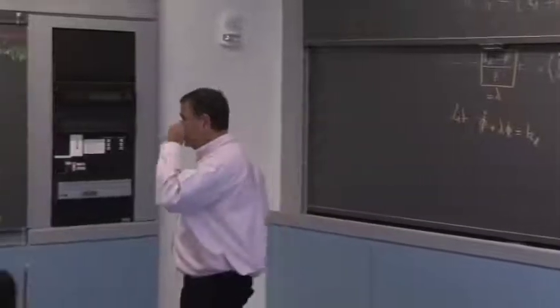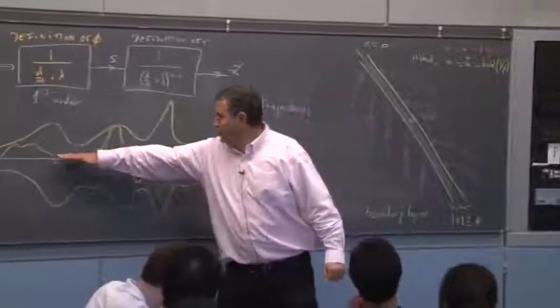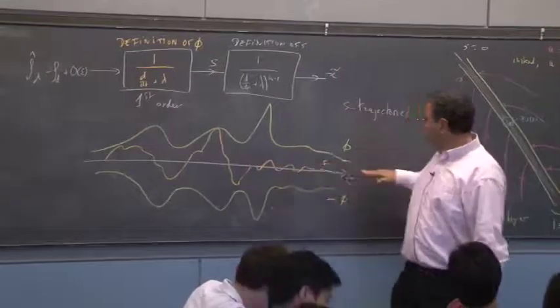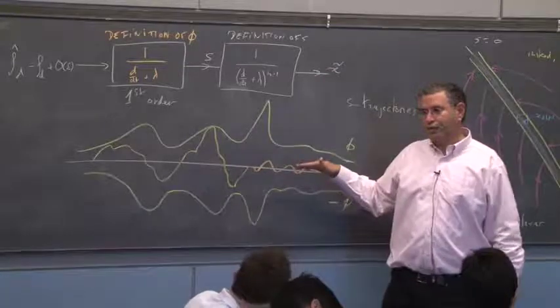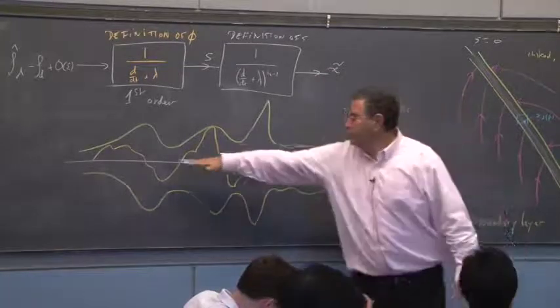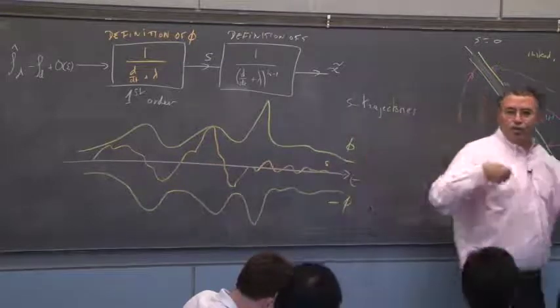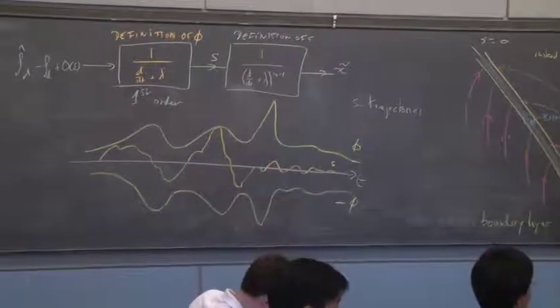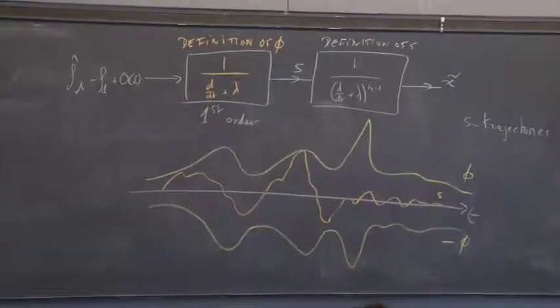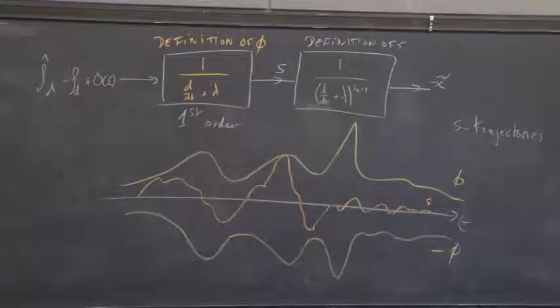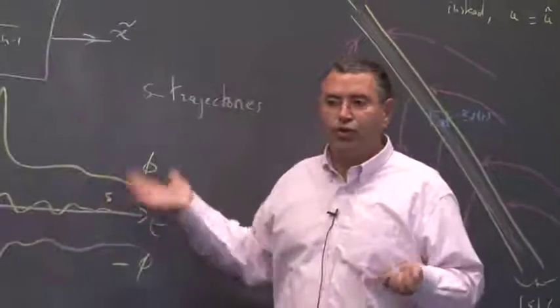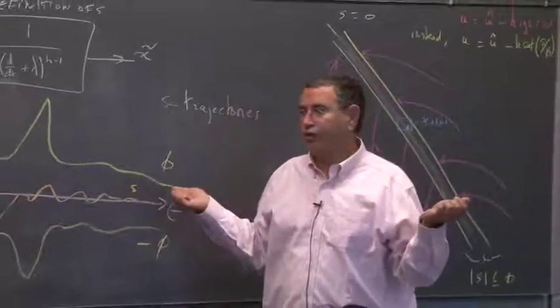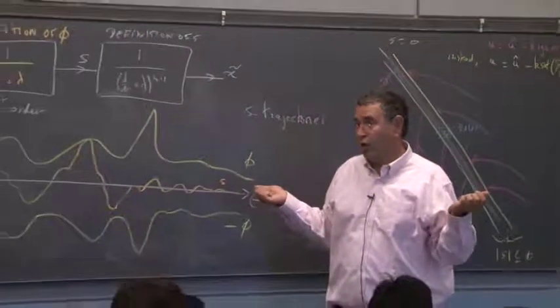First of all, suppose the orange curve is basically along the x-axis in this plot because phi is so much bigger than S, okay? Basically, you don't see the orange curve, right? It means that your assumption on the uncertainty are way too conservative, right? Because basically you picked phi, which was some filtered version of KD. KD was itself the uncertainty capital F, right? Fd, right? So if S is much, much smaller than phi all the time, it means that basically your assumption on the uncertainty are way too conservative, okay?